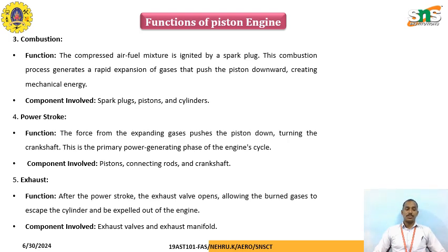Power stroke. The force from the expanding gases pushes the piston down, turning the crankshaft. This is the primary power generating phase of the engine cycle. Components involved are piston, connecting rod and crankshaft.